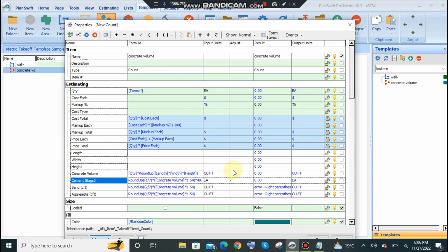Again do same process of shuttering calculation for our circular column. Again add in the estimating tab like this and put same formula. We have to add a diameter if there is a circular column. We must have a diameter tab here. So again select this formula, copy and just paste here.